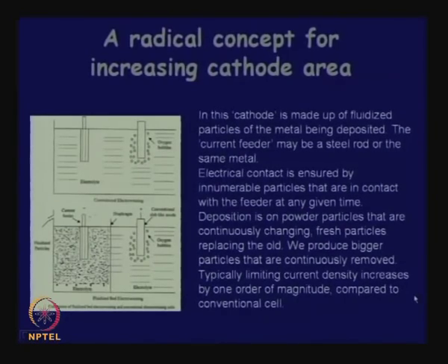Now, in principle this is very good. What are the disadvantages? There will be disadvantages. Firstly, you are not getting a consolidated metal layer on a plane surface. Secondly, you end up with powders which you may or may not want. If you want it, it is fine. Thirdly, you now do not have a static system. You are continuously pumping, you are fluidizing. So, that brings in more plumbing, that brings in requirements of handling the discharge, separating the coarser particles, constantly bringing in fresh finer particles, etcetera.